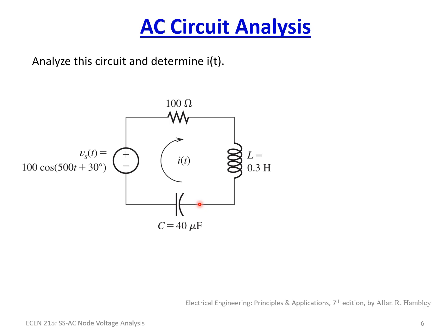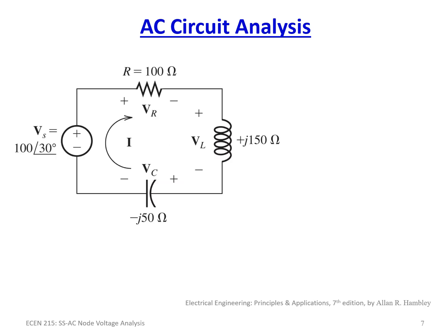Well, we can do literally the exact same thing now, except it needs to be the impedances that we add together. So if we know this impedance, and this impedance, and this impedance, so we know the 100 ohm, the 0.3 Henry, and the 40 microfarad capacitor, if we know the equivalent impedance, then we would know this circuit. So let's go ahead and do that. First step is to convert everything over into the complex form and phasor form.